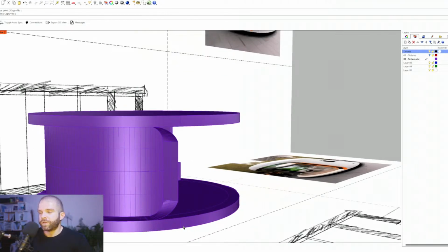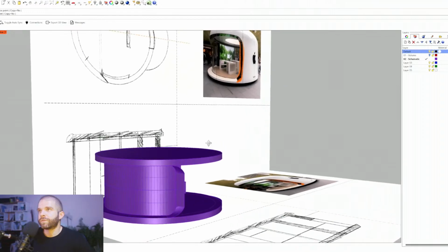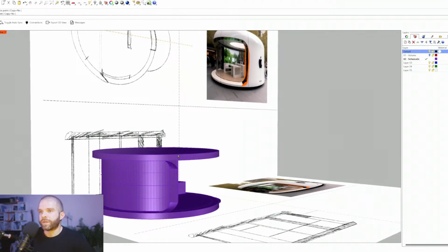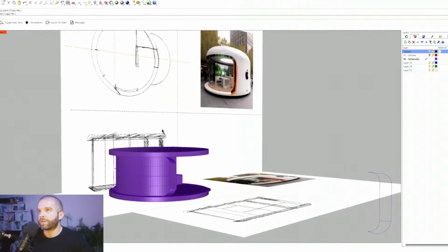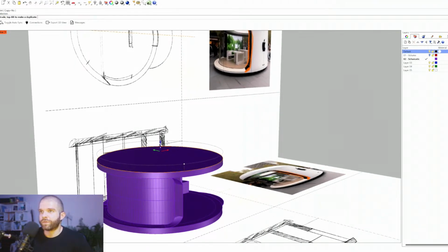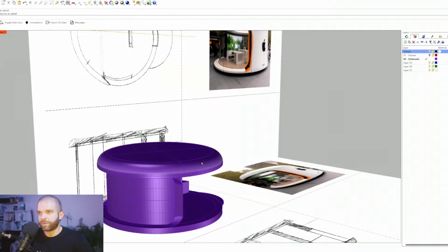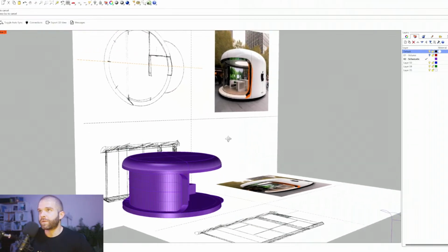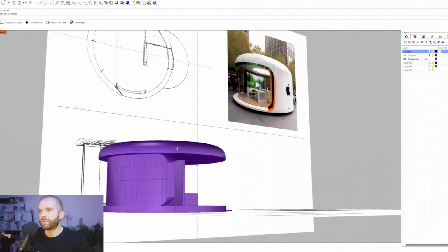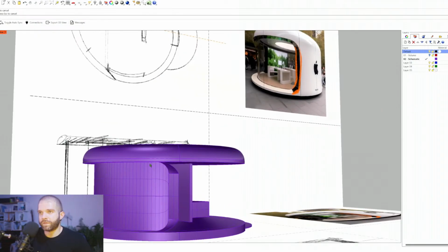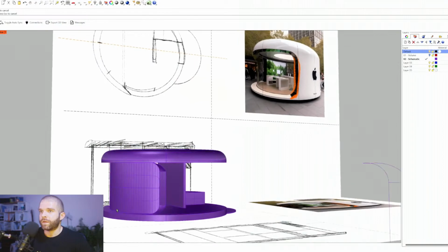Because essentially what I need to do, looking at the reference, is build out each individual part. So for example, I'd extrude this piece up. I can do a fillet edge on this top edge as we did before. Keep it at 2.8. Sure. That looks similar, but not exact. That's fine though.